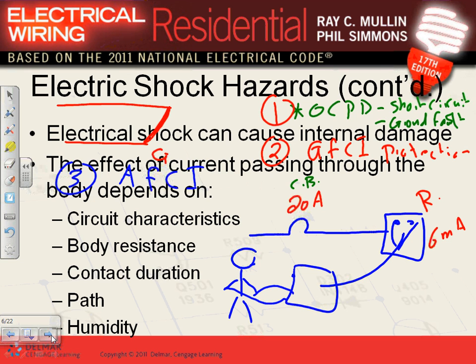The fourth protection, believe it or not, that we have is tamper resistant. Tamper resistant, I showed you guys the receptacle. Tamper resistance will protect a kid from putting basically one paper clip right into the hot and getting electrocuted. Like I showed you the other day, I gave you a tamper resistant receptacle. In order to engage the receptacle mechanically, you have to push both the hot and the neutral. Here's your fourth protection in this circuit, tamper resistant.